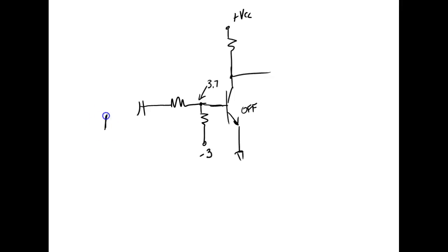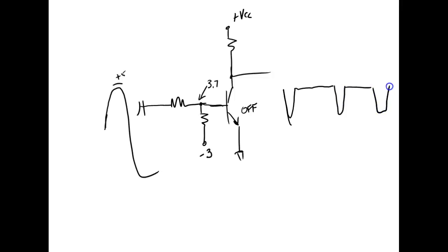So my input is changing, and then it drops down. So let's say this goes up to 5 volts. My output, and this is a common emitter, so it's going to be out. What we're going to get is just a little thing that looks like this. So is this going to be 180 degrees? It's going to be less than 180 degrees.